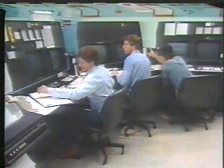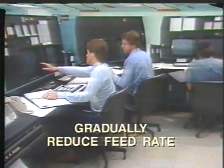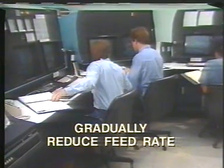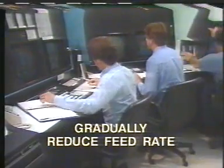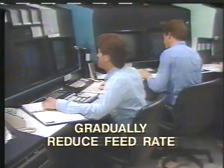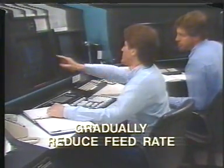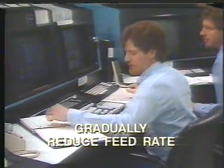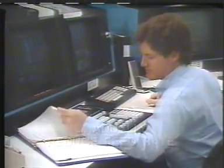The first step in most planned shutdown operations is to gradually reduce the feed rate into the column. As we reduce the amount of material put in the tower, the product output also decreases. By making gradual feed rate changes, the tower instrumentation can maintain the design conditions inside the column. This allows us to produce on-specification products while the feed rate is being reduced.